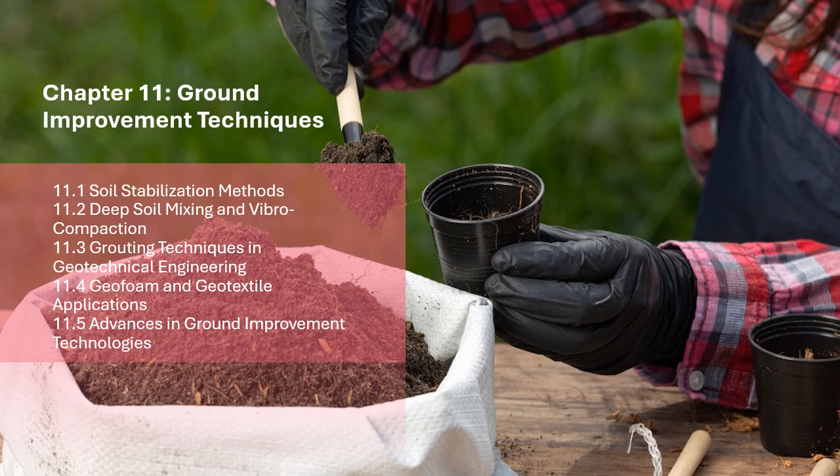Liquefaction mitigation. In regions prone to seismic activity, DSM can be employed to mitigate liquefaction risks. By reinforcing the soil with deep soil mixing columns, the soil's resistance to liquefaction is enhanced, making it more stable during earthquakes.